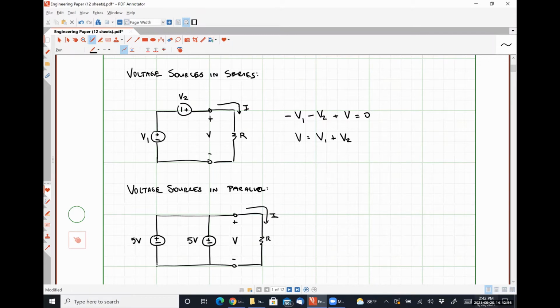This is what we do when we're wiring up solar panels and stuff like that. You often connect solar panels in parallel, and what that does is it lets each solar panel contribute more current to the load while maintaining that fixed voltage. That's also largely what I do at my job over in Bossier when I'm doing large-scale battery resources, voltage sources in parallel. So